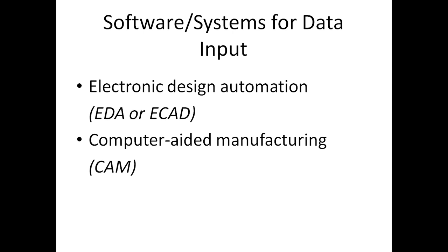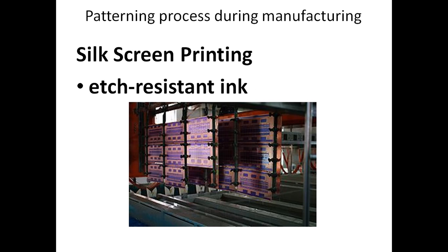Before the manufacturing stage begins, software designing and then the implementation of the design to the manufacturing system are performed. Electronic design automation or EDA software is used to design the layout, geometry, and orientation of an electronic element. Computer-aided manufacturing or CAM systems is then used to input the design data and other electronic variables needed onto a manufacturing machine. As mentioned before, PCB technology is used for simple to very complex designs.